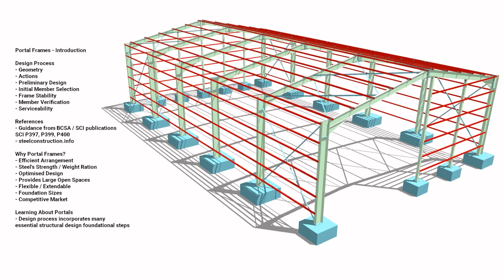And why are portal frames so popular? Well, for many reasons. The portalized frame itself is a highly efficient arrangement relative to its dimensions and the loads it caters for. Steel as a material complements it. Steel has an excellent strength to weight ratio. Portal frames are fairly common and well tested and documented, and therefore have been well optimized over time. And because they allow for a big open empty space, portals can be repurposed fairly easily or extended, so they can be well future-proofed. And because of the efficient design, it is lightweight and it lends itself to minimal foundations. There are quite a few suppliers for proprietary products for portals, and therefore it is also a competitive market.